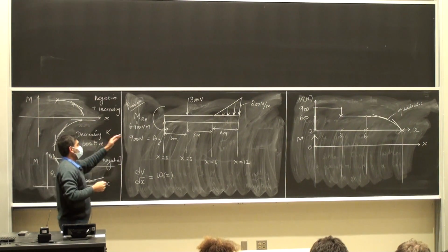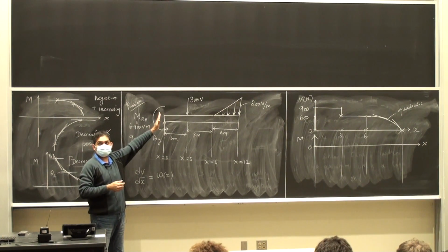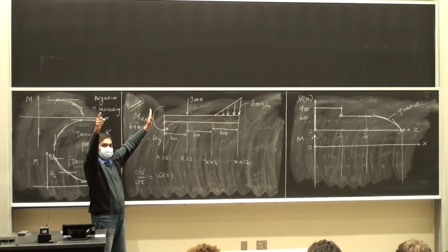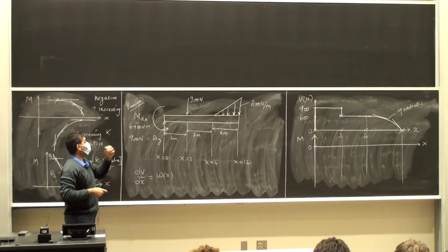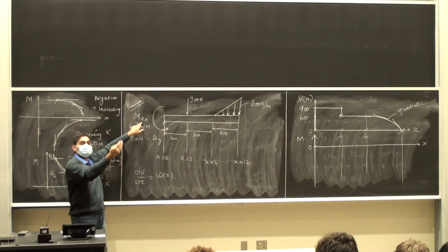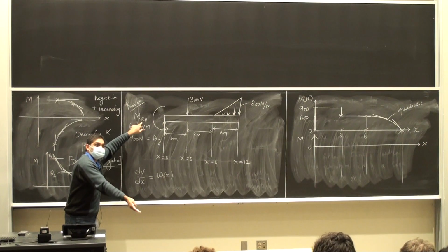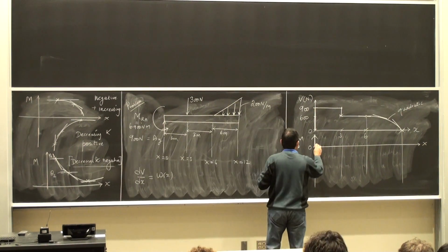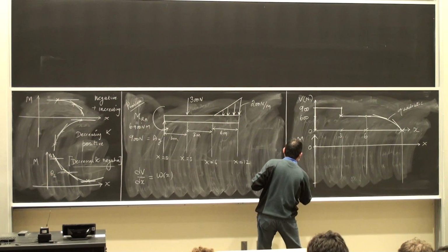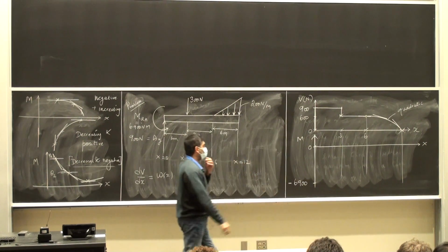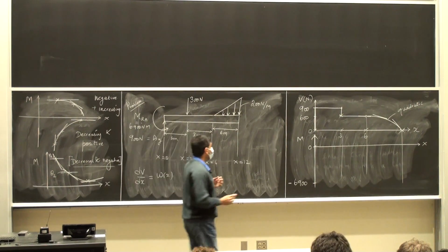Help me out here. At A, what happens? Yes? Negative jump. Why is it negative? It's because this is a counterclockwise couple moment acting at that point. So I'm going to drop down to negative 6,900 Newton meters starting at A. And M is in Newton meters.